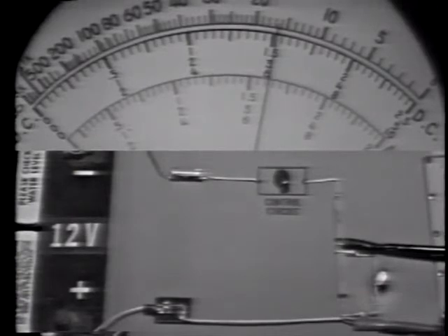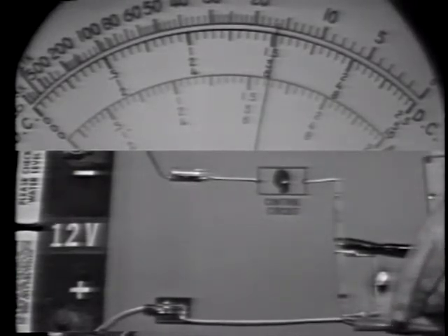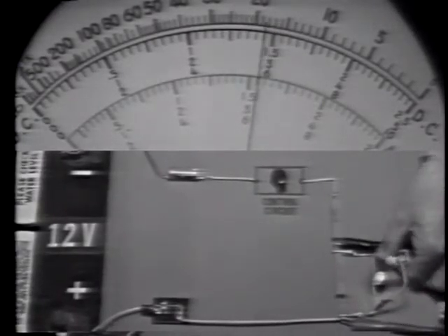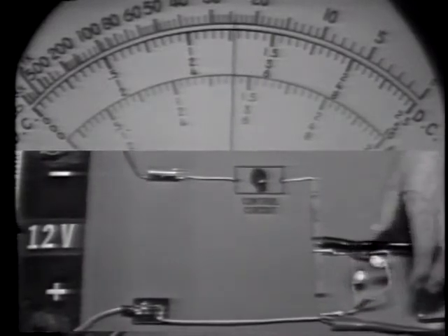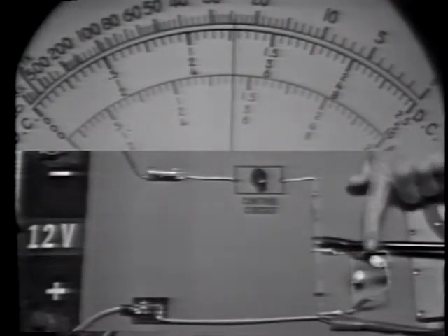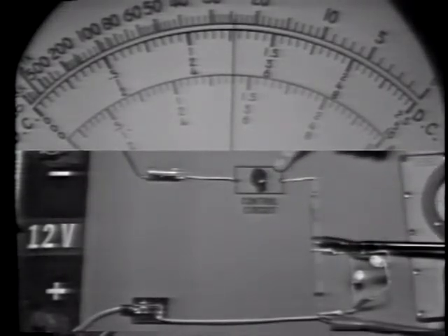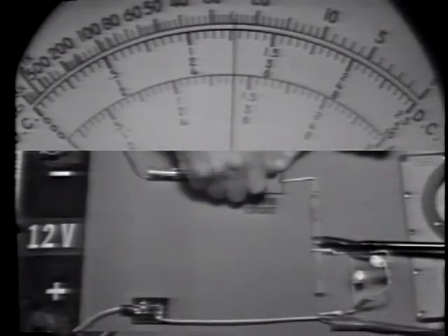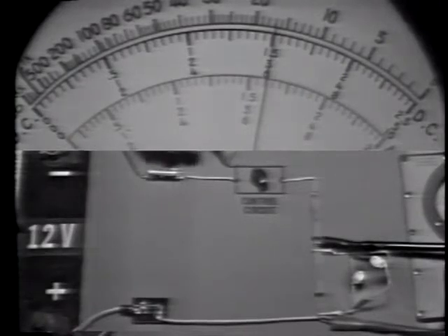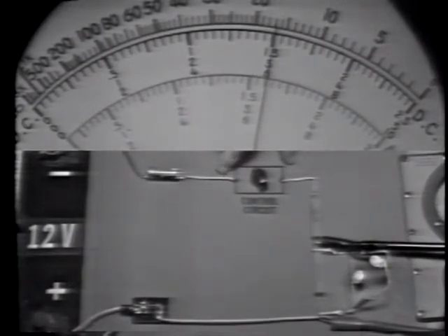Now suppose that we need another light out here. In other words, more load on the circuit. Watch the voltage as we load the circuit more. Well, you see the voltage has decreased. However, as soon as the load starts changing out here, the control circuit detects this change. It changes resistance. Well, it's a little bit touchy, so let me get it right on 6 volts. It changes resistance and decreases the voltage across the control circuit. The decrease in voltage here brings the voltage to the load device back to 6 volts.